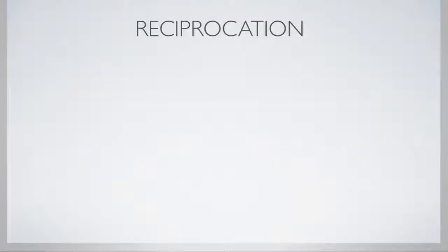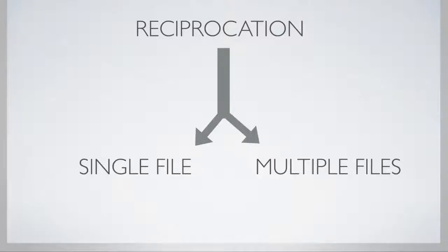So the main difference here is that when we talk about reciprocation, we really should be talking about two separate flavors of reciprocation. One is the more recently touted single file reciprocation, and then there is also this lesser known alternative, which is the use of reciprocation motion with more than a single file. Essentially cutting down the motion of cutting and divvying it up between more than a single file, using 2 to 3 files, and in the process have certain advantages that a single file doesn't have.